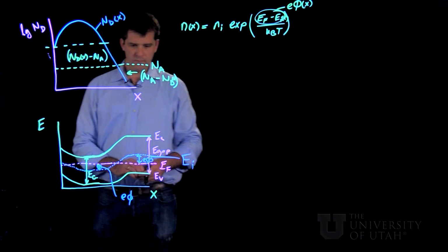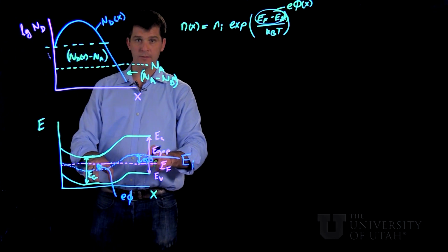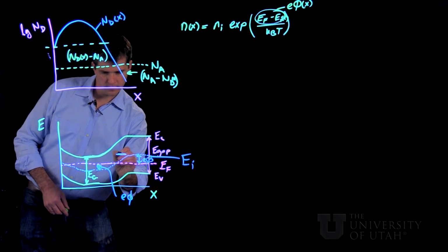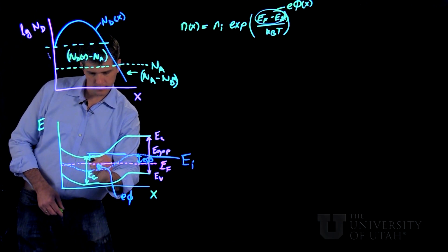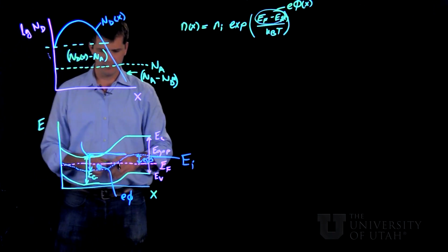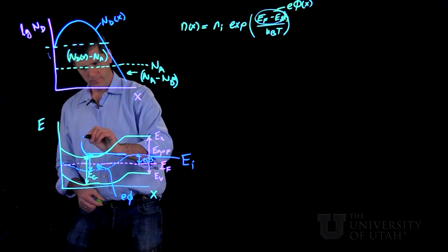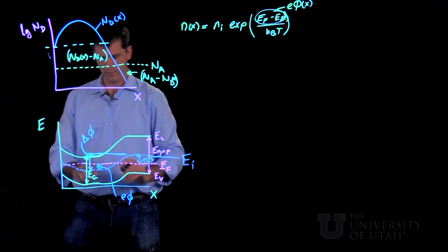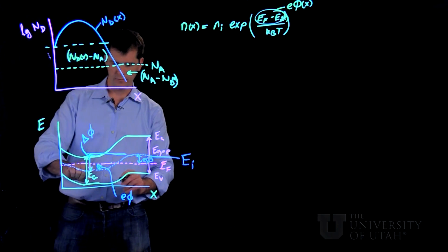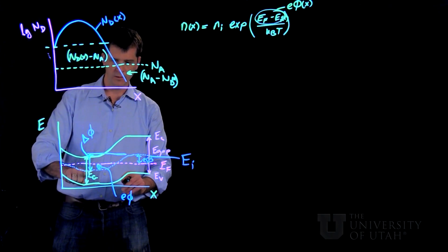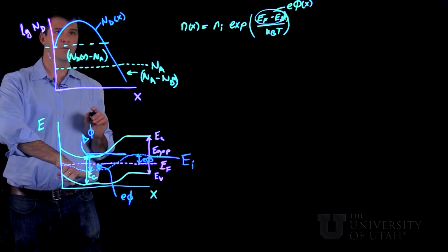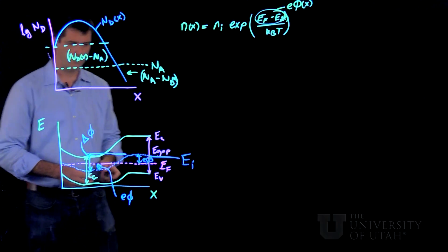So the difference in potential would be known as our built-in potential. And so a total voltage difference, and this is really a pseudo voltage internal to the material, not an externally applied voltage, occurs between these two points. So if we take this as our reference, we could calculate how many volts equivalent the presence of those dopants have induced inside the semiconductor.